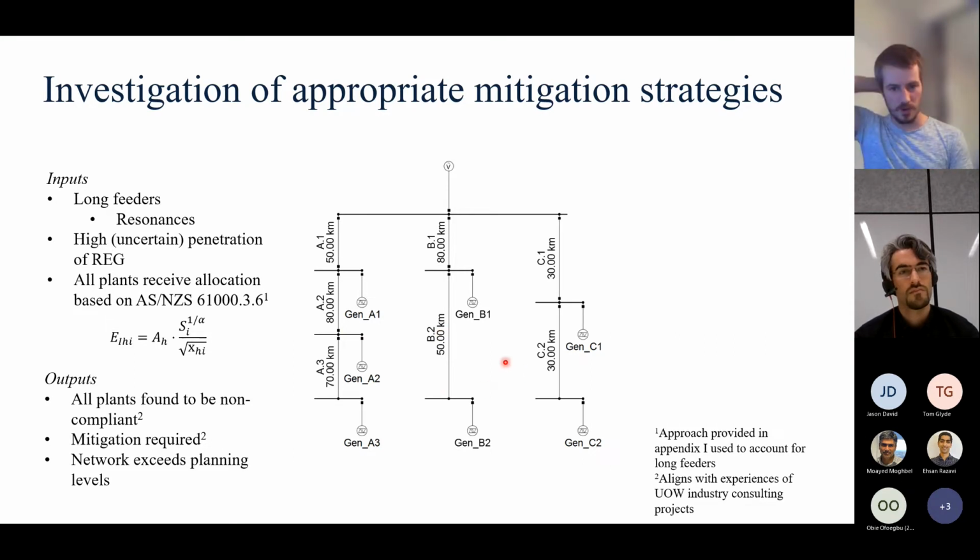So it's really a matter of, like I mentioned, it's almost like whack-a-mole. You knock it down where it's a problem, and you can keep knocking it down until everyone's happy, everyone's connected, and there's no issues with harmonic distortion. So it's really a matter of what the end game is, and if the end game is to get all of these 3, 5, 7 generators connected, then it would just be a matter of getting those connected, having the filters required, and then moving on. That would be it. But realistically, that's not that simple.